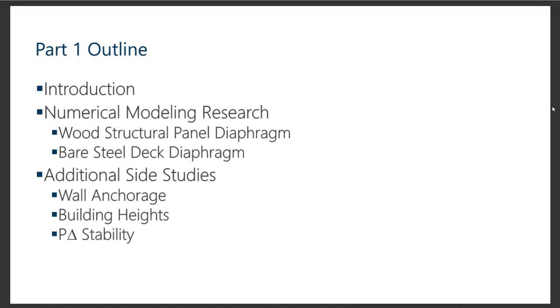My outline: I'm going to be going into an introduction about this type of procedure, diving then into the numerical modeling research that was done, and looking at both a wood structural panel diaphragm and some discussion about bare steel deck diaphragms that were done. And then some additional site studies were looked at regarding wall anchorage of these buildings, building heights, looking into the effect of that, and some P-delta stability studies that were undertaken.